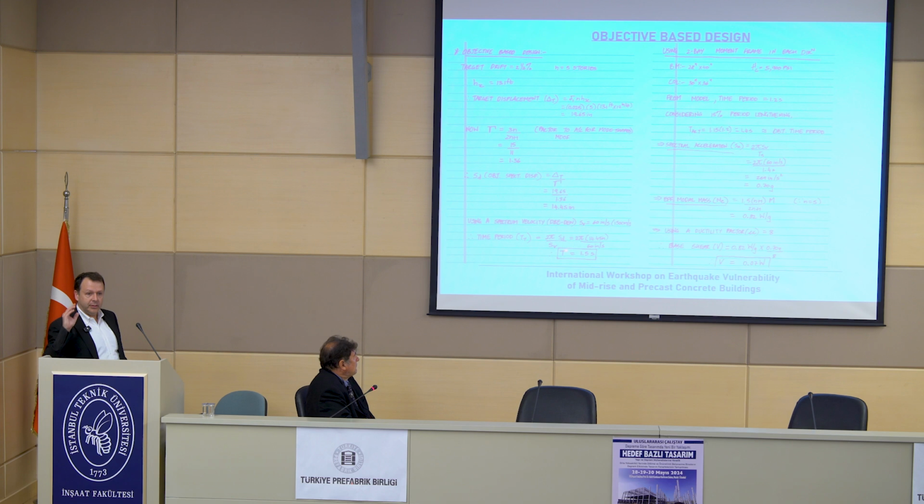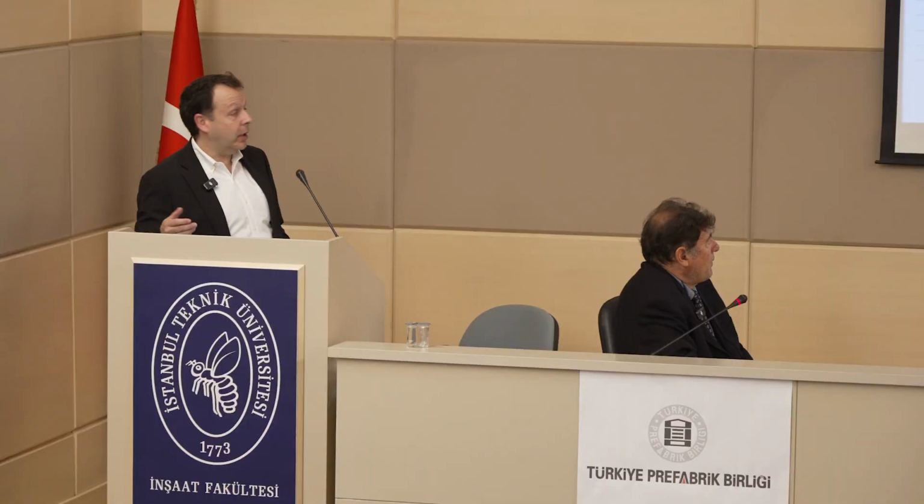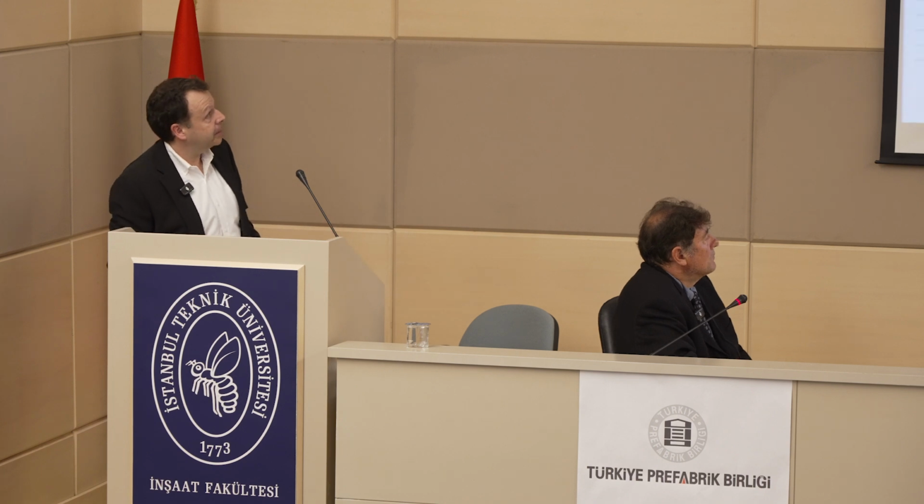Then we're using this Denali earthquake in terms of spectral velocity, defined 60 inches per second, so about 150 centimeters per second, or 1,500 millimeters per second. And with that, you define your period there just by spectral displacement divided by spectral velocity times 2 pi. And so that you have your target value. So very close to what you had, 1.54, 1.5 here.